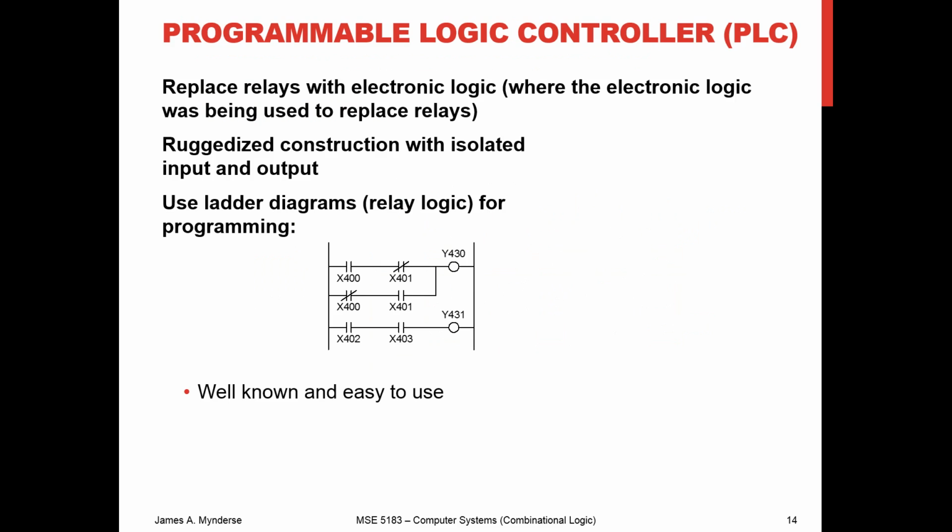Another thing that you'll see is programmable logic controllers, or PLCs. We're not going to use them in this class, but they use the same logic idea as relays, what you might call a ladder logic. And so you're going to lay them out in the same sort of way that you've got symbols for relays that are normally open, symbols for relays that are normally closed. You can put them in parallel, you can put them in series as is shown, and you've got light indicators to indicate that something has happened. It's a relatively well-known, easy-to-use sort of process.